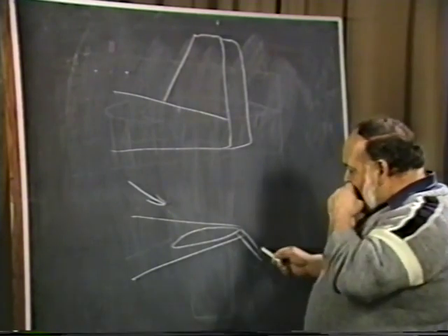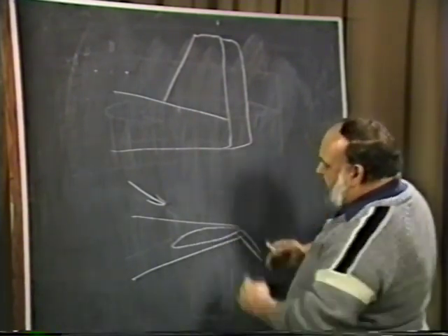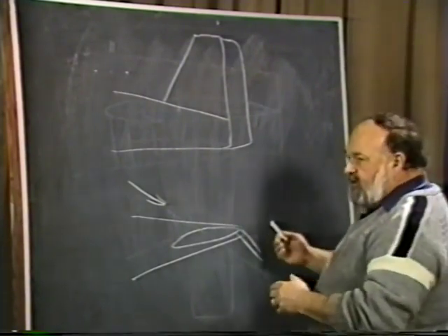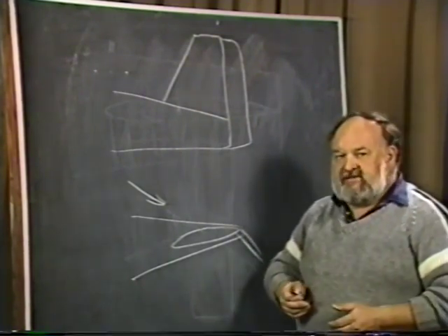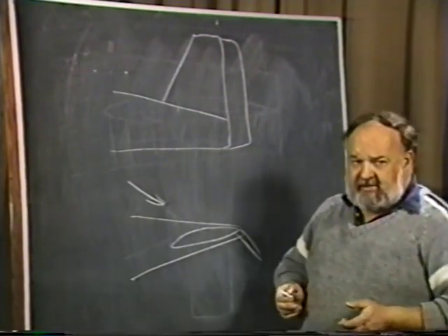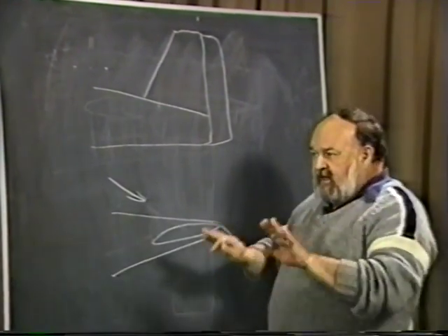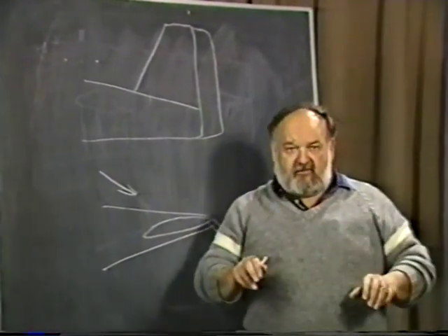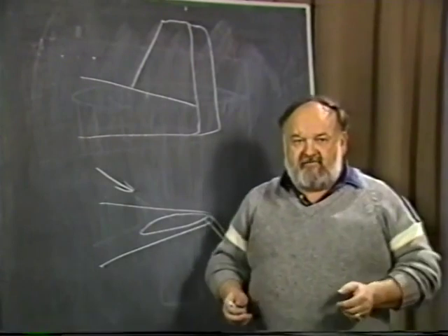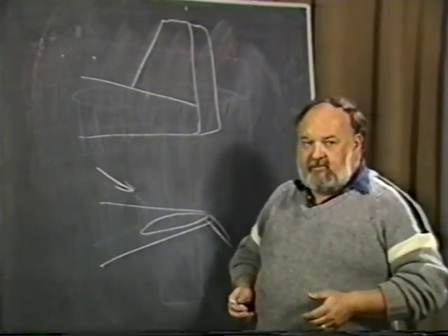If you go too far sometimes with this rudder, it will actually yaw the airplane so much that you get rudder lock. The rudder will literally snap over to the side. You don't really want to have that. I don't know of any general aviation airplanes like that, but back in the late 30s and the 40s, there were certain fighters that were built that way. If you'd sit there on it and yaw the thing an extreme amount, all of a sudden the rudder pedal would snap over in that direction. And you had to sit there and fight real hard on the other pedal to pull it back in.